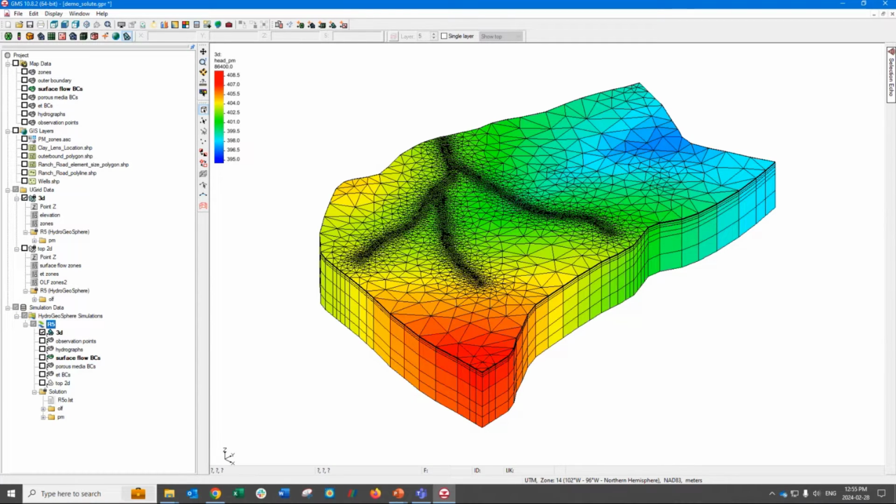And then there's a question here from Walter. He found the choose elements between raster surfaces command particularly useful. How can I use it here? Well, the beauty of the GMS interface is that you don't really need to use any commands from the HydroGeoSphere context to select elements. Choose elements between raster surfaces could be used to define the location of a clay lens, for example. That's actually something that is built into the HGS tutorials for this interface.